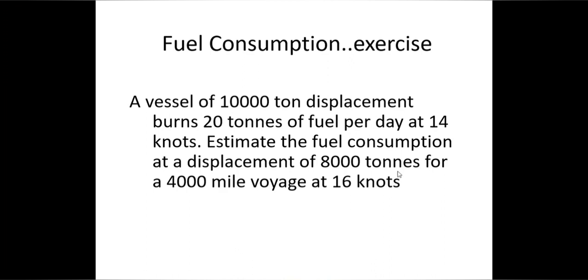So use the formula which we have discussed already and calculate the fuel consumption for a particular voyage with 8,000 displacement. First data is given at 10,000 displacement, 20 tons per day fuel consumption. So everything is given, you have to just use the formula and calculate. Let all of you do this and then we will compare the answers and see if there is any difficulty. Also tell me and we will discuss that.